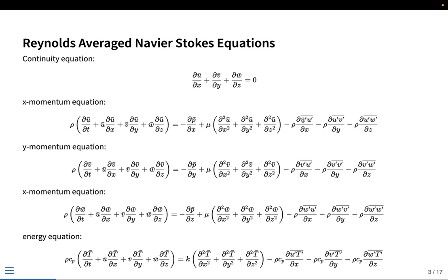the fluctuations. So for example, if you are measuring velocity at a particular point inside your domain, you happen to observe a profile that is not completely predictable with your models. Whatever that unpredictable component is, you are treating it as if it is random noise, and that random noise is the reason you are calling them fluctuations. That would be this particular term u prime. Because I'm defining it as random noise, I'm not able to say what the value of u prime is deterministically, but it will be a stochastic variable which keeps changing with each and every measurement.